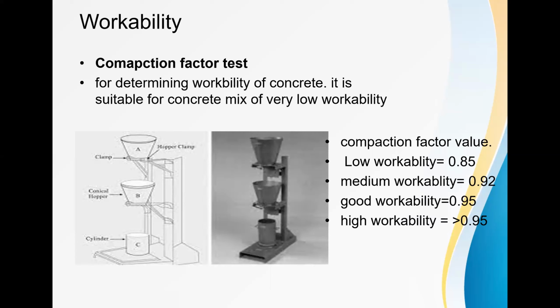Next is the second test, which we call the compaction factor test. For determining the workability of the concrete, it is very suitable where the concrete has a very low workability.